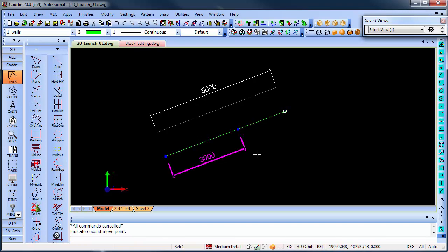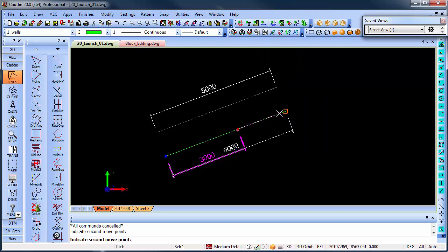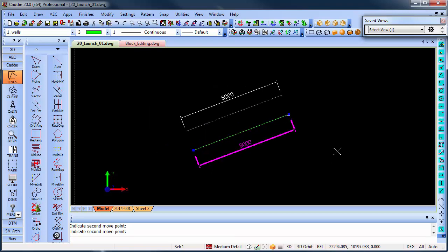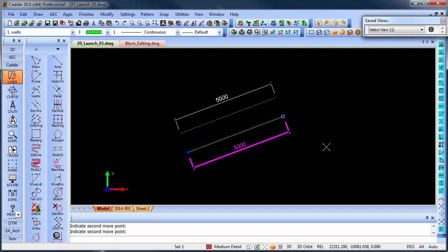The same can be done for dimensions. So once again, if I move that dimension grip point, I can either project it or snap to the line at the bottom. And that is how you can use your line extension snap along with your polar tracking or polar snapping to make things and work like that a lot easier and faster.